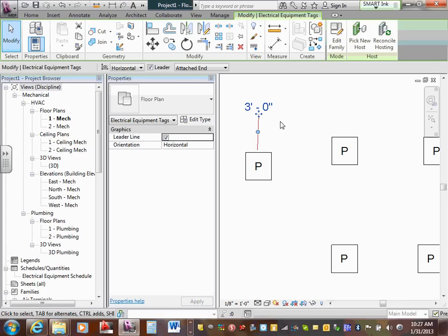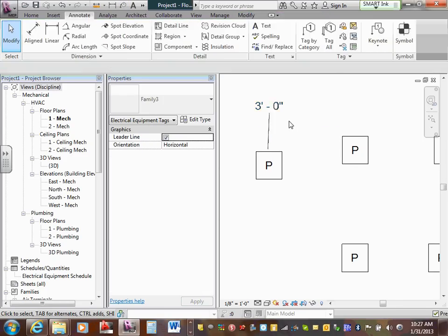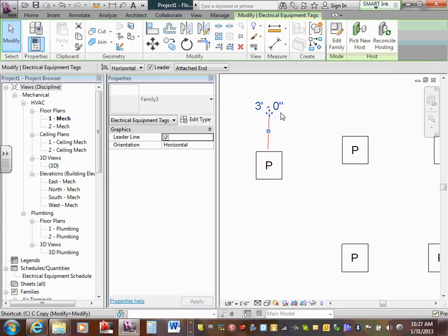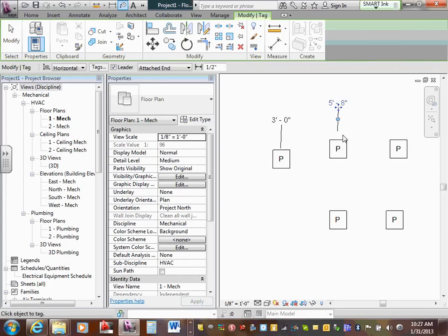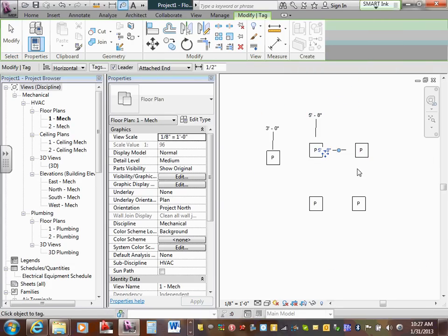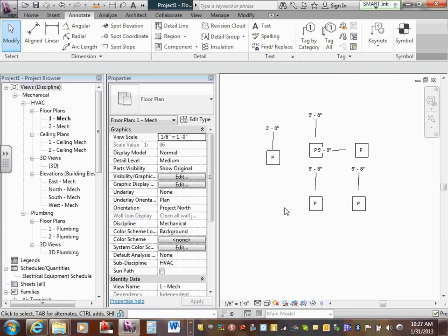And it's tagging the length of that. You can only do that with shared parameters. You can't do it with instance or type parameters. The reason we can tag it is because the length is a shared parameter. And we know how to edit a tag and add to it, but creating a tag was the issue.